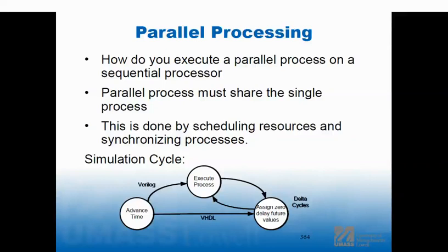So what the simulator has to do is say, okay, I'm not done with that, but I'm not going to increase the simulation time. The simulator has this clock that keeps increasing over time, and your internal clock and delays and all that happen. But when 2 things happen at the same time in the simulator, it can only calculate 1, but it knows that they're concurrent. So it has to put off that calculation, but it can't advance its real time.